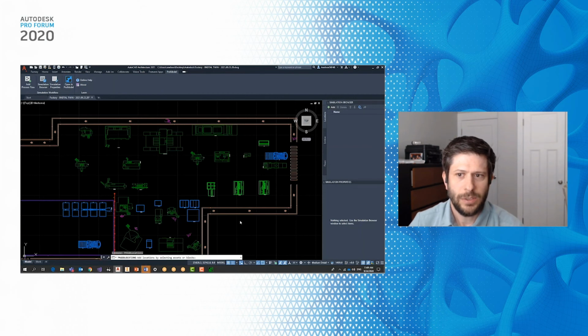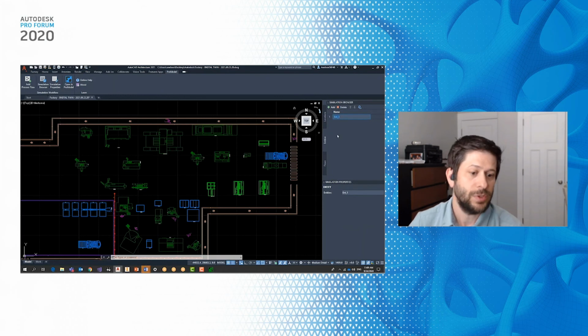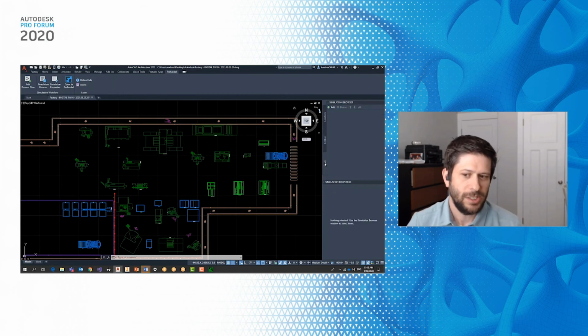Locations, if we want to mark an asset that's inside of our drawing, we select Add. And down in the command line it says pick the locations. So I could pick these locations and simply hit enter, and it will mark those and add them as locations to be used in ProModel. Entities, we can hit add, and that will automatically, since it doesn't exist in the layout, it'll automatically just give us an entity name.